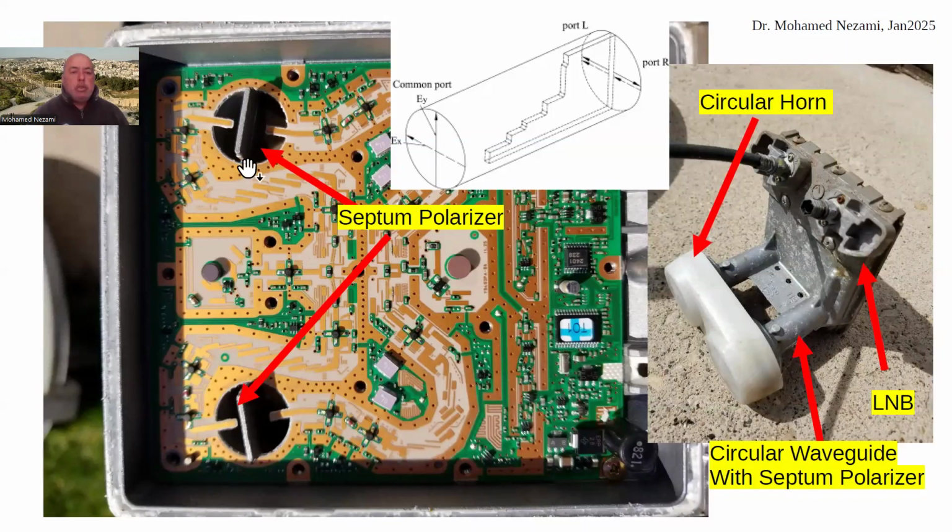So this is a low-cost DirecTV. I think this used to be from Hughes. This is a dual horn. You can see there are dual horns in here with the circular waveguide that goes into this compartment and comes out with two IFs. You can get these from junkyards, flea markets, or laying around in your house, or you probably still have one that you're using for TV, or you can get ones that are similar like these, which I will cover today also.